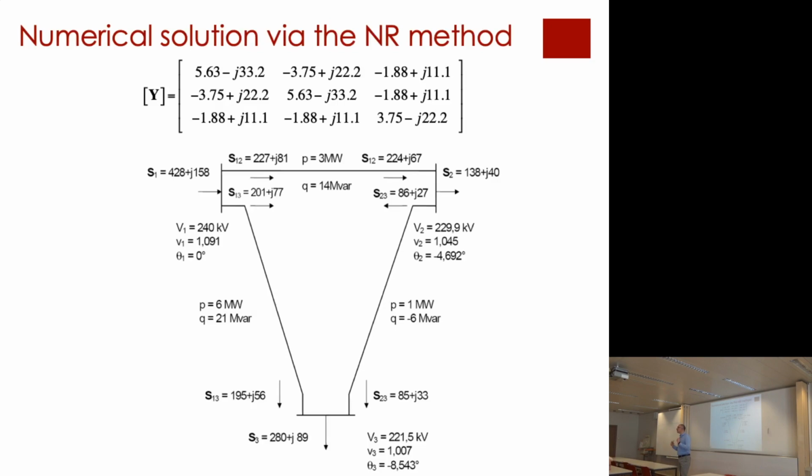There are, however, tricks to control the flows on the lines via devices called FACTS, F-A-C-T-S, Flexible AC Transmission Systems. Okay. However, these devices are tremendously expensive, and they are allowing you to directly control the flows through the lines. Normally, if you don't have these devices, you control indirectly the flows through the lines by just controlling the injections. Okay, that's it. All the rest is a consequence. And unfortunately, this consequence is via nonlinear equations.